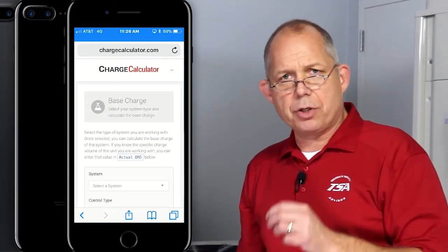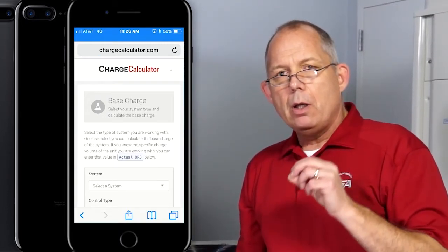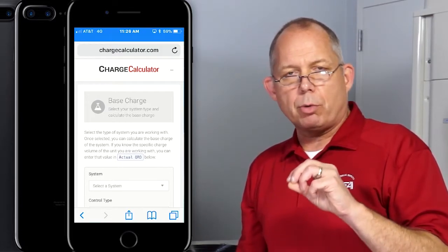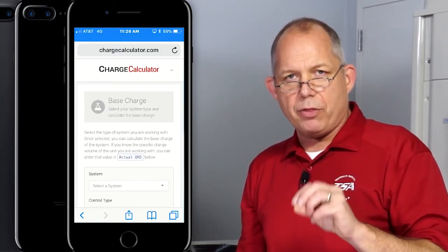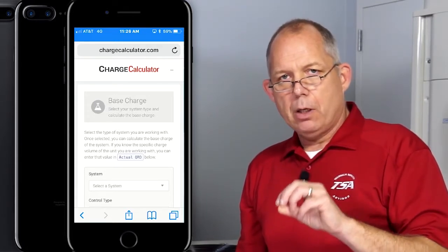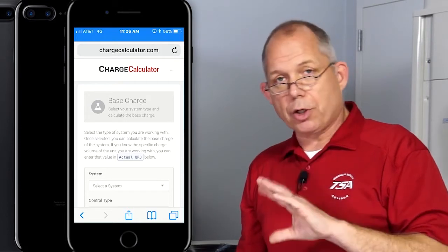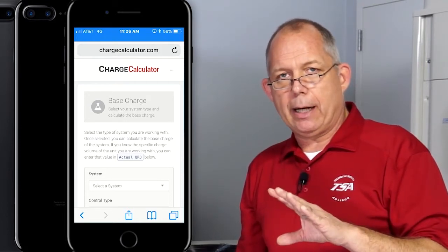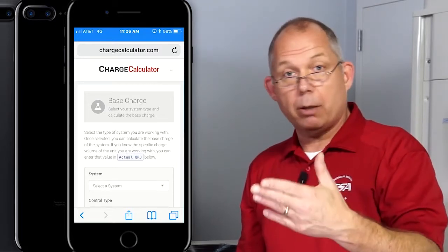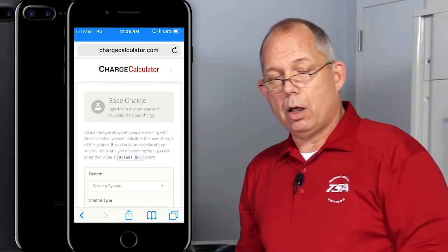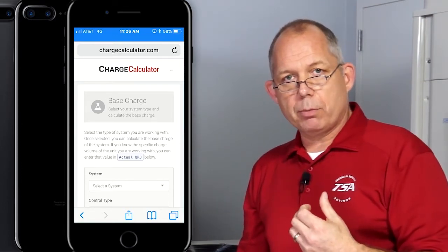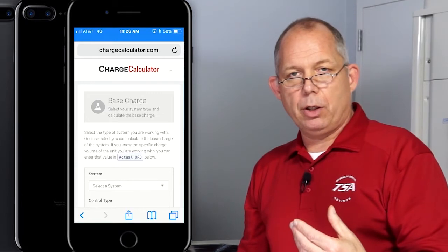First thing it's going to ask you for is your base charge. As always at Nortech Global HVAC, we're going to want you to refer to the QRD that came with the unit to ensure that you have the correct charge. If you're unsure of that charge, we can look at that a little bit later in the app. But if you're unsure if you have the correct factory charge, if you're coming up to troubleshoot or diagnose a system that may have a refrigerant problem, remove the refrigerant from the system, refer back to the QRD.